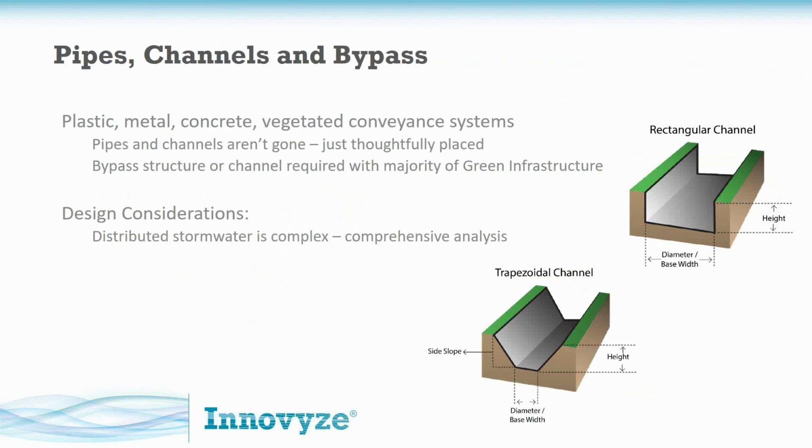Well, design considerations, even in a standard traditional layout, where you have a pipe network that dumps into a pond, this is still important. But especially when you have a distributed stormwater system, or smaller ponds and facilities all across your site to give you more space and developable land, yet still meeting your pollution reduction, you need a comprehensive analysis to assess that, right?